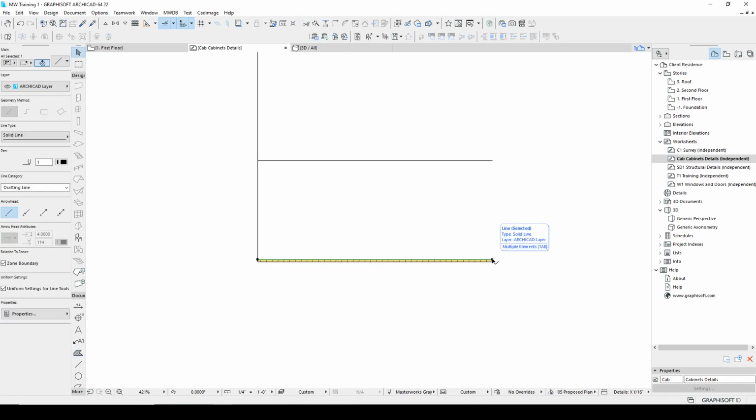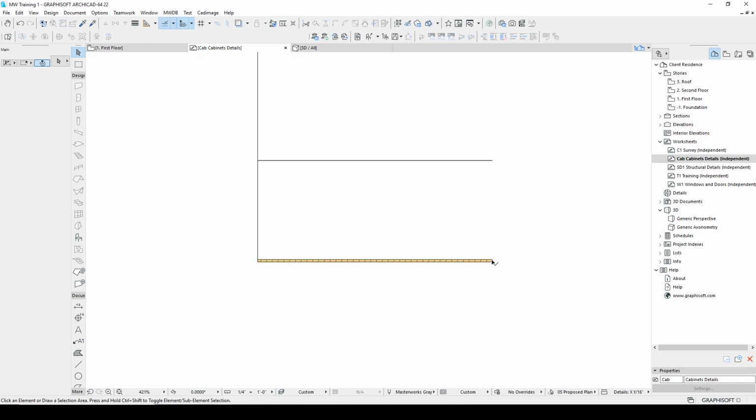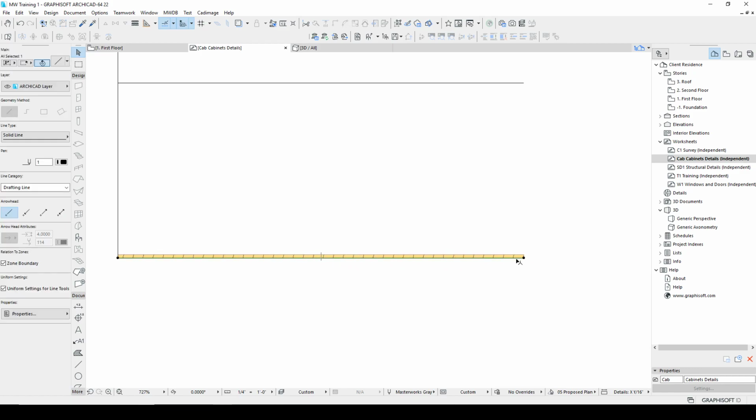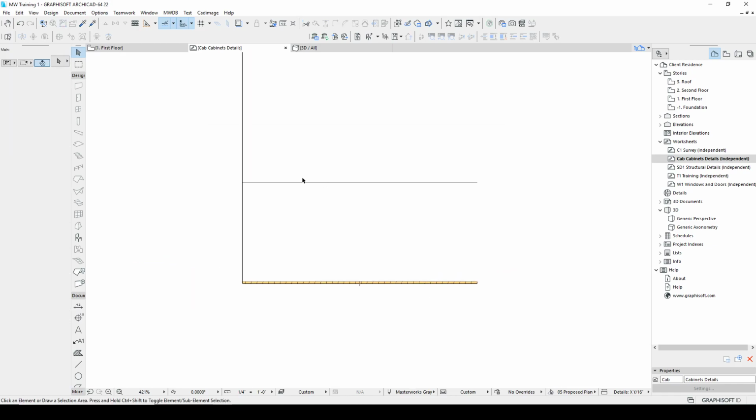And now I used Shift to enable my selection tool, and it found the line. If it didn't find the line, I can hit Tab, and that'll scroll me through my options, but it found the line, so I'm going to just delete that. Again, I'm trying to use as few lines as possible. And even this line becomes unnecessary, but I'm going to leave it in there anyhow. Those will be just a few lines.